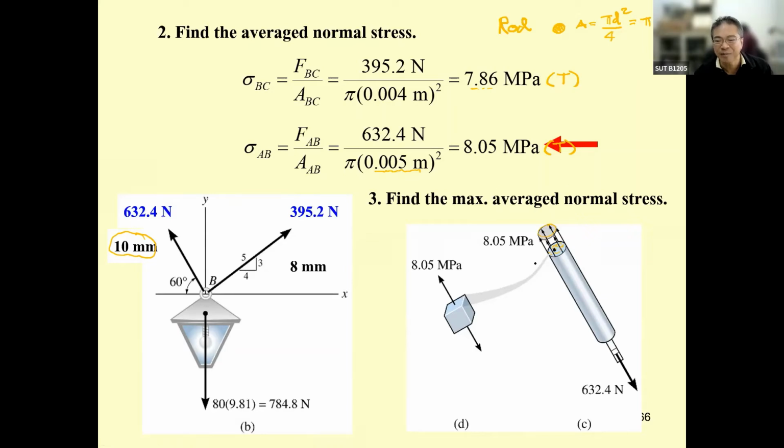And if you take a material point, you cut a small material point to consider, you may draw this one. This one we call the stress element. This is the stress element due to the axial stress, and if you are more specific, it is going to be tensile stress. There is a lot of nomenclature. Okay, that may be the same, and I would like you guys to get used to it.